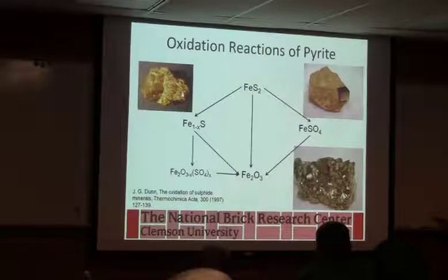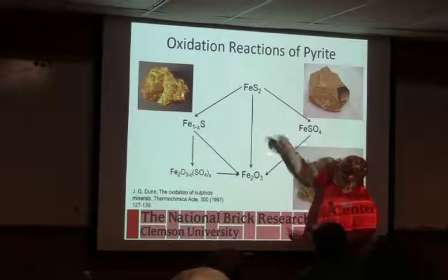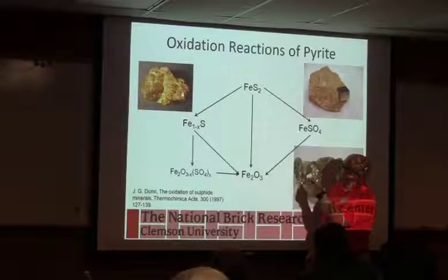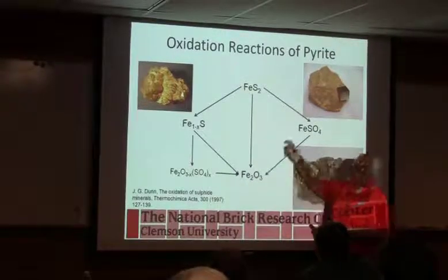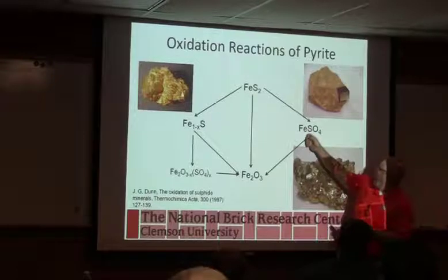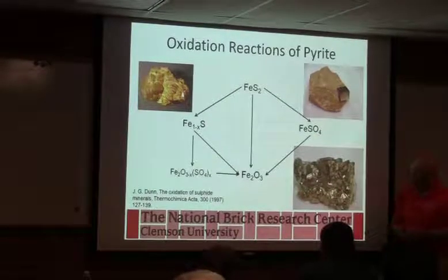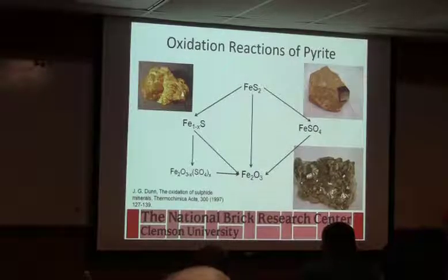But it will sometimes pre-oxidize. So there are people up north who have this. It's easier to oxidize this than this if you have enough oxygen, so they don't stockpile their material. They dig it out of the ground and go straight to the kiln. Because if they let it sit in the pile for any period of time, it actually gets harder to get all the sulfur out. The problem with not stockpiling is you have to be very careful in your mining, or you're going to have all kinds of variation coming through the plant.